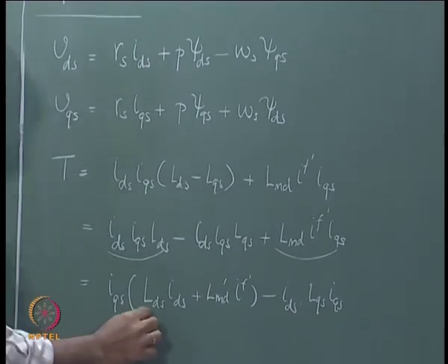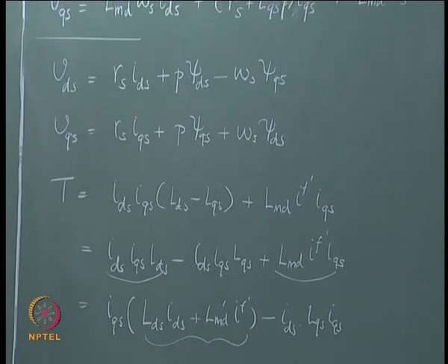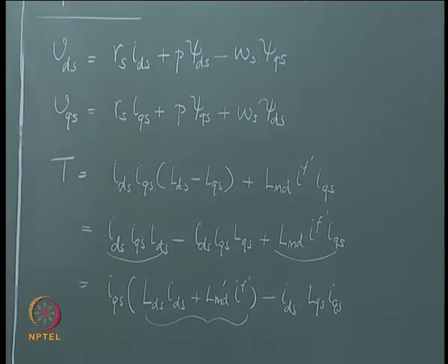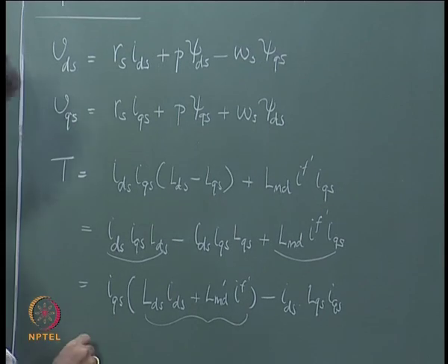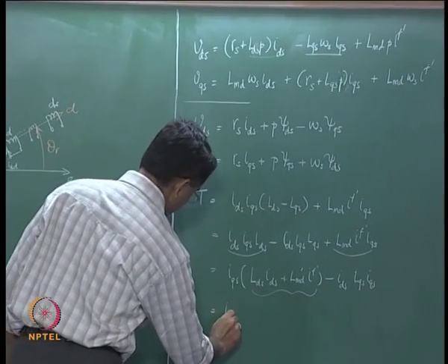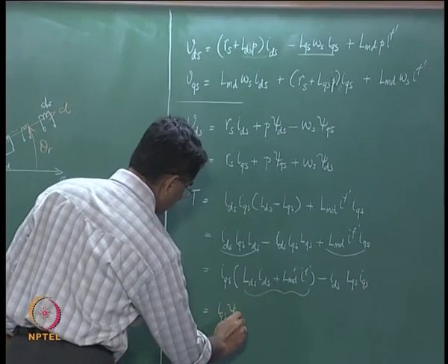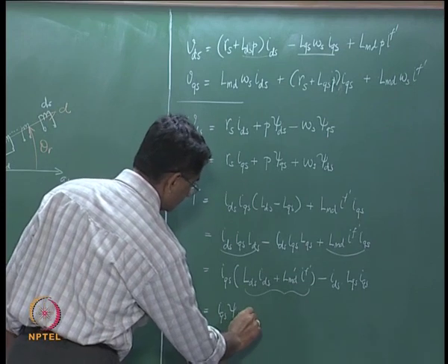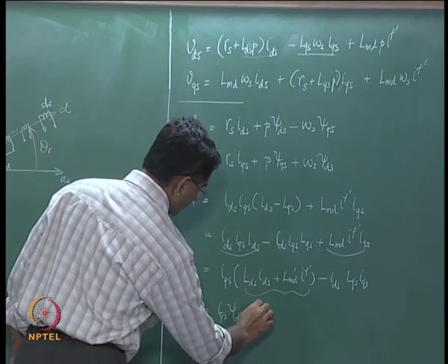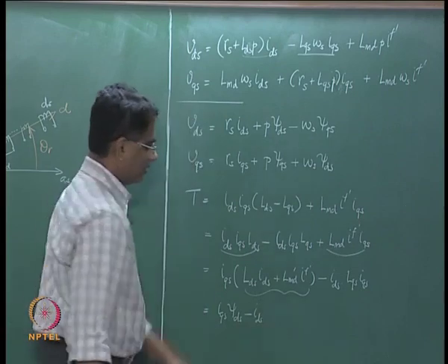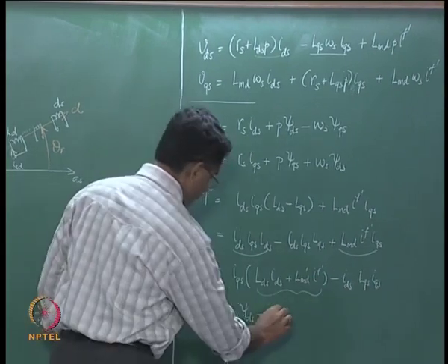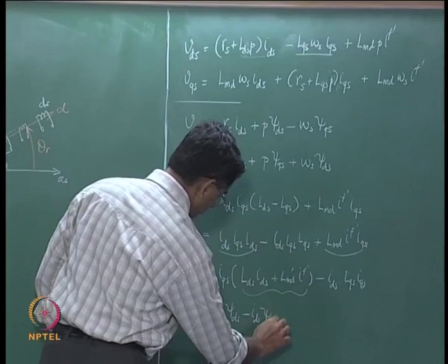Now, this term is nothing but your psi ds as we have defined, and therefore, this can be simplified as IQS into psi ds minus IDS. This term is nothing but psi QS, so that is psi QS.